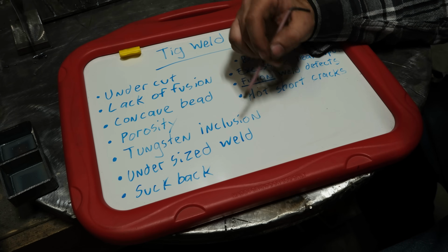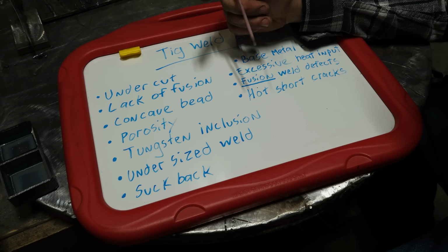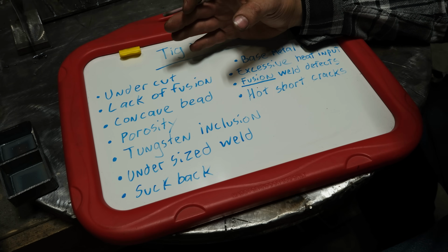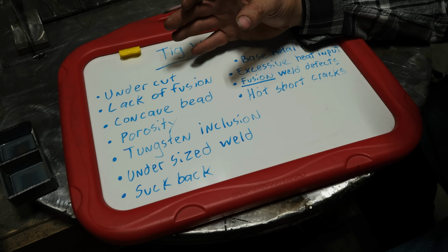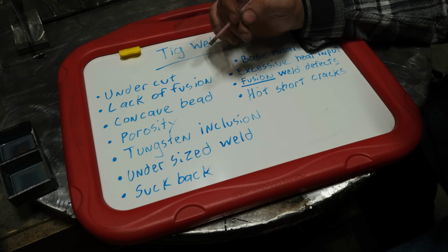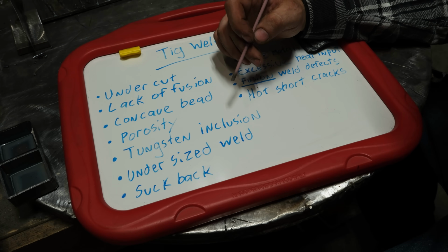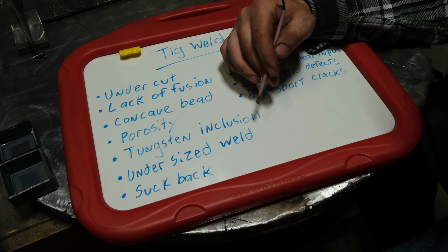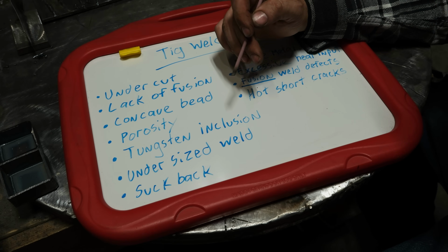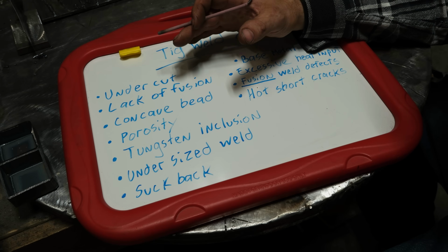But anyways, back to what I was saying, undersizing your weld. A proper stick or MIG weld on 3/8 material might be a 3/8 throat depth weld, so a pretty substantial weld. You do not want to get in the habit of putting, say, 1/4 inch size welds on 3/8 material and saying it's good enough because it's TIG. You're going to be mistaken, depending on what you're building.